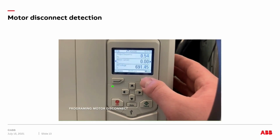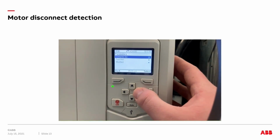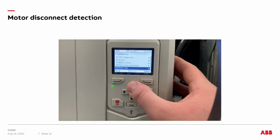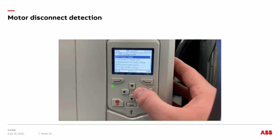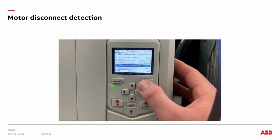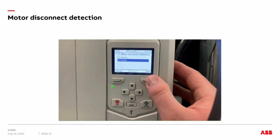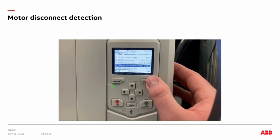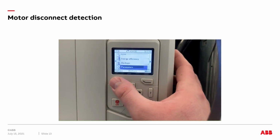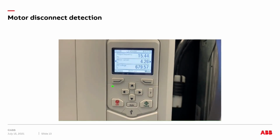So now let's actually show off motor disconnect detection. I want to program it in really quick. As you can see, I went to main menu and all the way down to parameters, and then I'm going to go into group 95. Once I get into group 95, I'm going to go down to parameter 95.26. Once I'm in 95.26, it's defaulted as disabled, but I'm going to enable it. Now that I have the parameter enabled, I'm going to start the drive again, let it get up to speed, and then I'm going to open the motor disconnect.